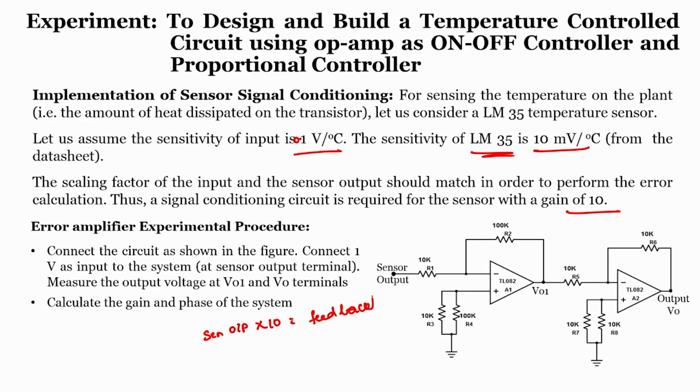So, in order to do that, you can go with different things, but the only thing is that input impedance and output impedance, the loading effect should be properly carried out, as well as the output should be of same phase, right. So, in this case, the whole idea is we have to get a gain of 10.